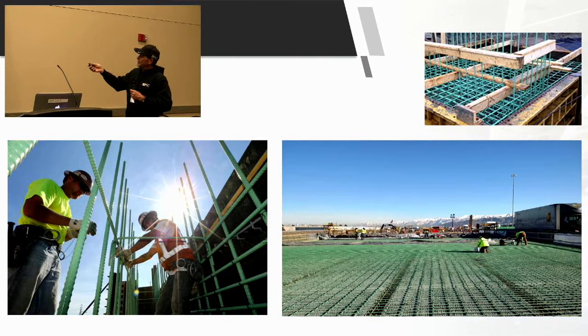On deck rebar, the one thing that I like to do is I like to stand off to the end, just sight down all my bars to make sure that they're within the 1/4 inch that they're supposed to be, and they don't have big wags going down their longitudinals or their horizontal bars and their transverse bars. Another thing on these, even though everything looks nice and consistent and you would think that your bars are in there, make sure you go out and you count.